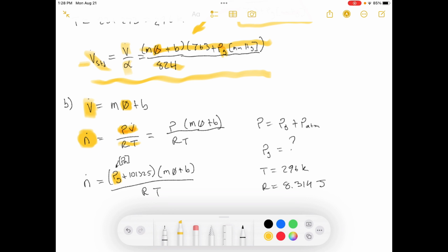So I guess if we assume that it's the same gauge pressure, whatever the same is. Okay. This time I converted it to pascals. So we've got our newtons, we've got our R reading. If we convert the gauge reading into pascals, it needs to be compatible with whatever R units you're using. So if you're using joules per mole Kelvin, then you would need to use pascals here for the pressure. Okay, so that's why I converted this into pascals for the atmospheric pressure.